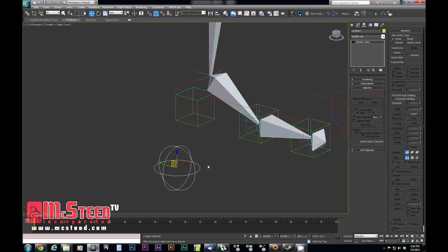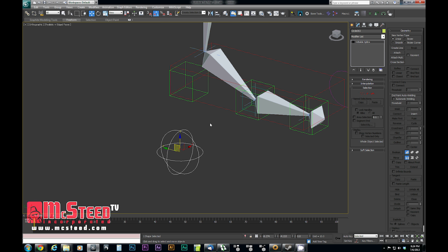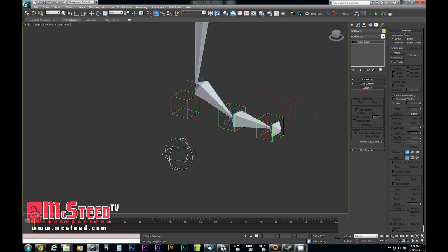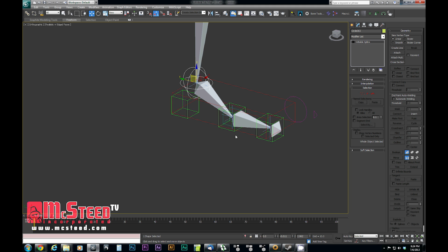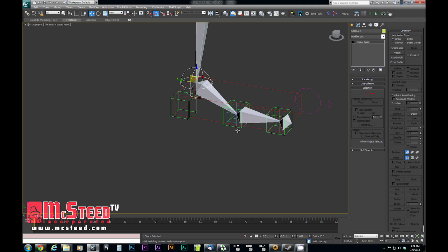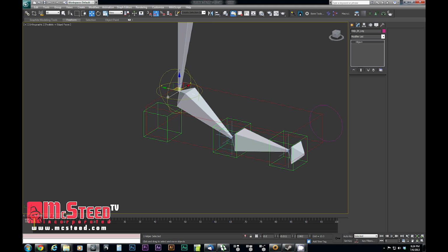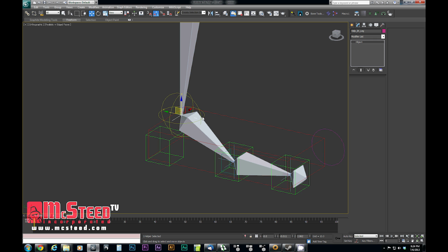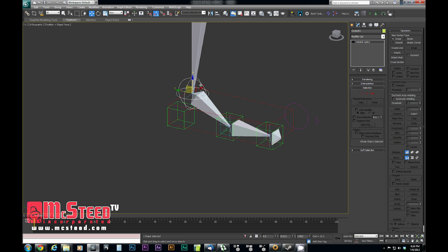Okay, for the last control I created a spline object that is just 3 circles. It sort of creates a sphere-like icon, and this is going to be for the ankle. Now in my foot setup, since I like the foot to pivot from the ball, I don't necessarily want it to pivot from there when the foot is in the air. I like to treat the foot as FK, or the way you would animate the hand of a character. So I'm aligning that to the IK chain that represents the leg. And so now when I set this up finally, I'll be able to rotate the foot from that spot.